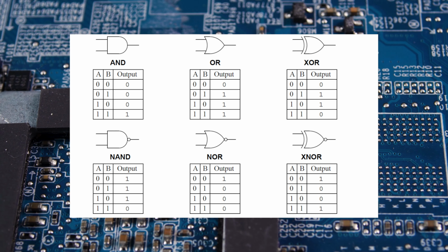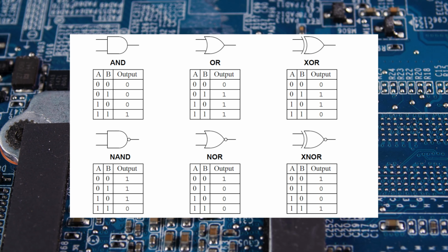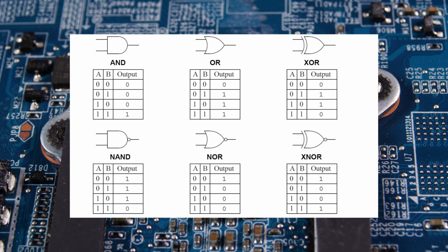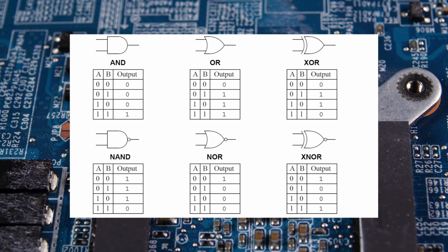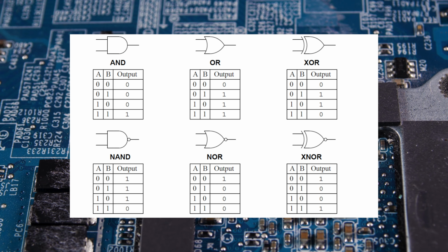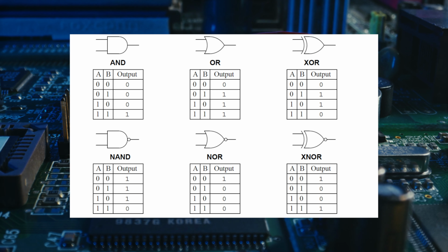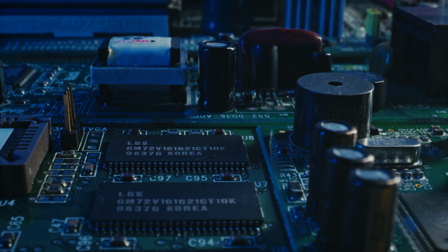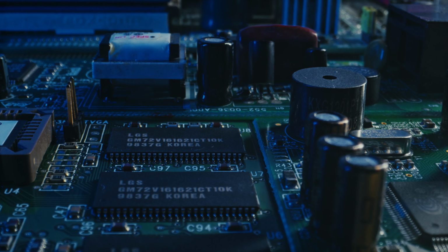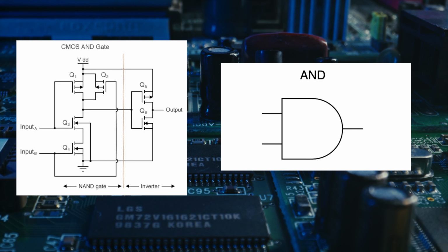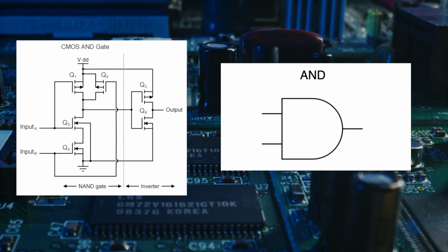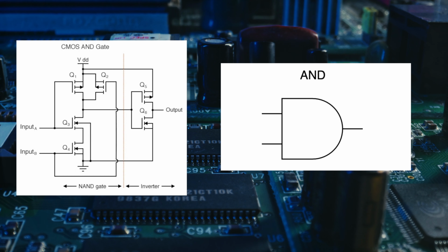As you can see, given two inputs A and B put through a system will give you the output of that logic gate. Another thing to keep in mind is that a logic gate can have an infinite amount of inputs but a single output. The system or gate will not change its properties however many inputs are present. Now, to show you how the logic gate relates to transistors, here's a diagram of a simple AND logic gate with two inputs A and B and a single output.